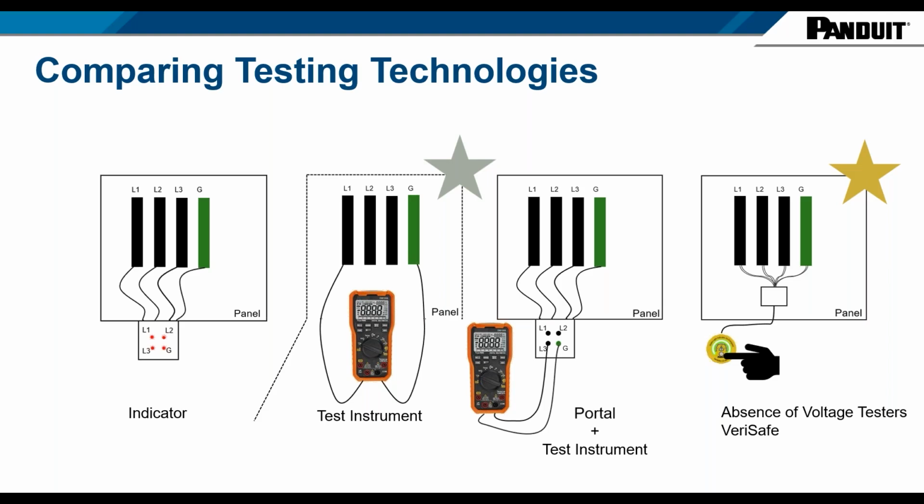You've got to put your PPE on to do that, right? Because before you have verified absence of voltage, you have to assume that there is still voltage present, which means you need to protect yourself based on the cal rating of that panel. And that comes with, I'm not going to get into that, but that comes with different criteria for what PPE you need to be wearing.